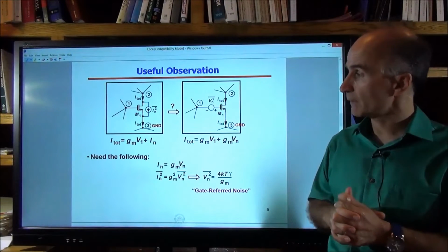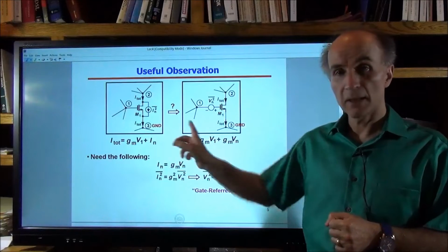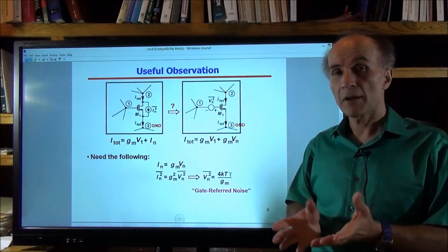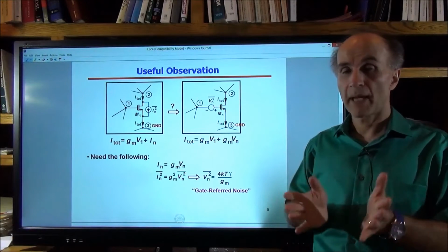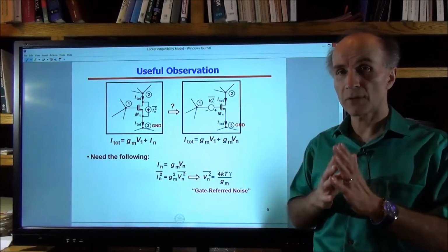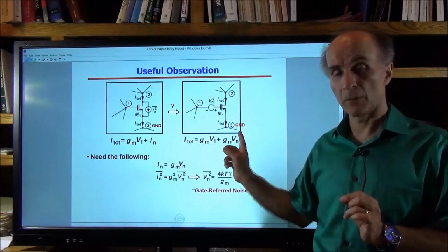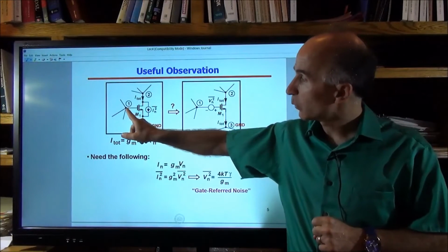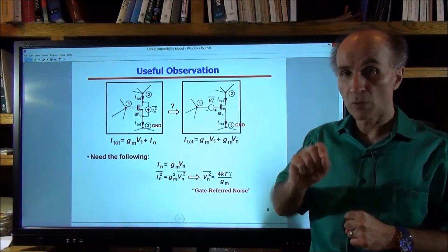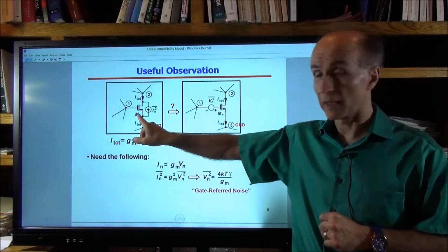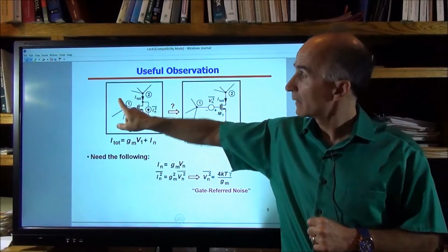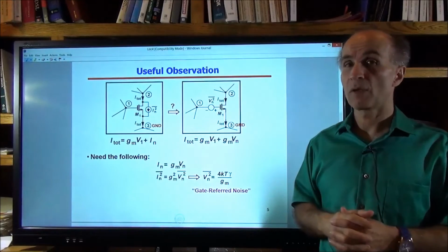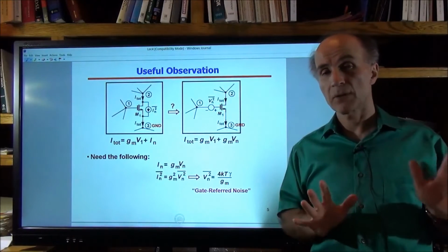And to prove that, first of all, we assume that node 3 is a reference point, reference voltage. You can call it ground, even though this node may not be the actual ground of the circuit. Just imagine that we are measuring all of the voltage in the circuit with respect to node 3 in both cases. All right. Now we also notice that node 1 may have some noise in it arising from M1 if there is any feedback path this way or this way. So the voltage at node 1 is not necessarily noiseless, even though everything else in the circuit is noiseless.